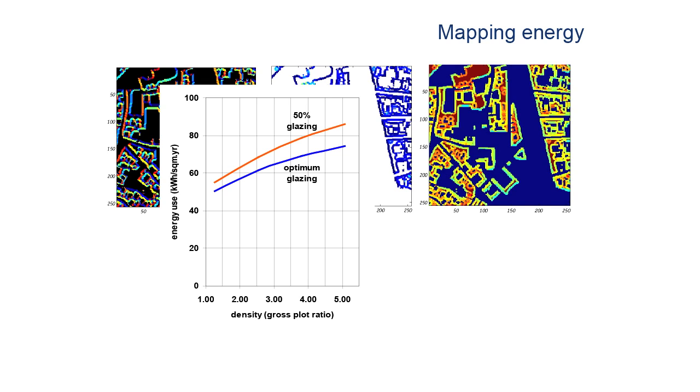And as I say, Henning Larsen architects demonstrated that there are ways of getting around that, still increasing the density, but managing to achieve lower energy consumption. So from this simple plot, you can see that if you double the density from, say, a plot ratio of 2 to 4, you increase the total energy use by about 25%.